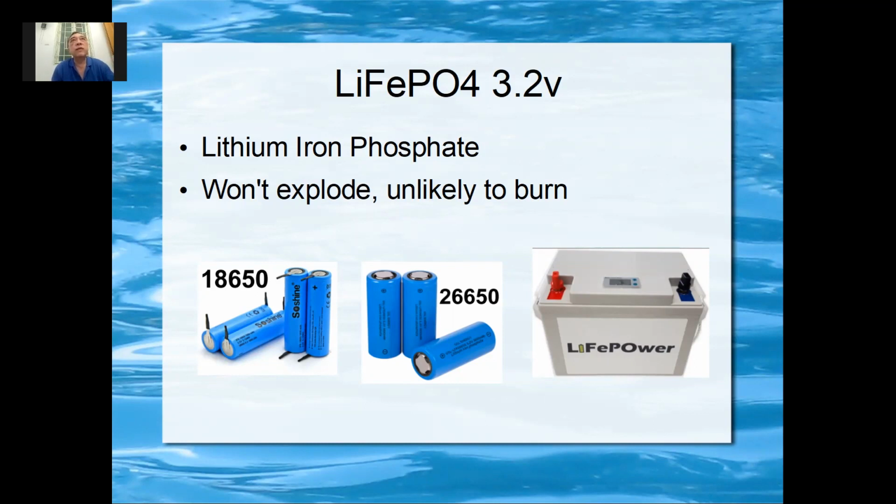So what to do if you want, let's say, 48 volt? Then you must buy a battery pack that is already 48 volt, one battery pack that's 48 volt, because built in there is a battery balancer that will balance out all the charges for the batteries internally to get 48 volt. If you want 24 volt, you must get one battery pack that is exactly 24 volt. Don't get two 12 volt and connect them. It's not advisable.